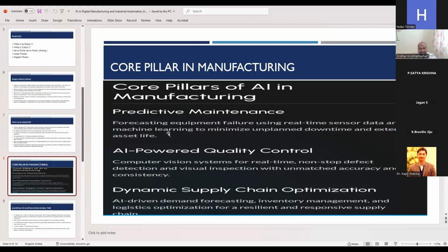Preventive maintenance is based on the calendar, right? Irrespective of how you carry out the preventive maintenance for our DGs and compressors, whether running or not, after 30 days or after certain hours, we'll be changing the filters or oils, similar to our car. If it runs for 10,000 kilometers or 3 months, whichever is earlier, we take it for service, right? That is preventive maintenance.